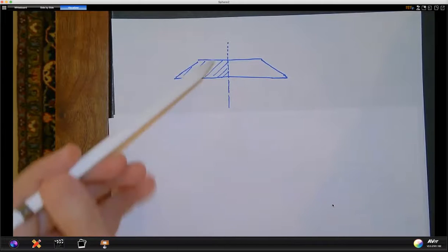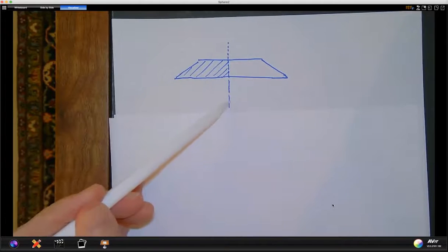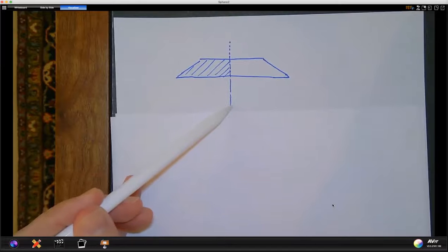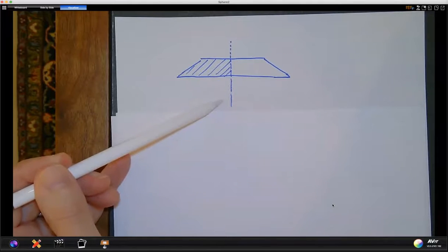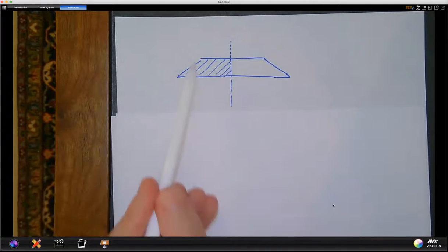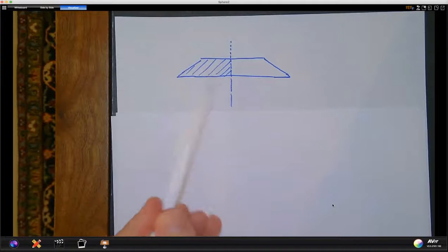And if you happen to be interested in a point down here below the surface at some depth z below the base of the embankment, you can figure out A, B, and Z, and you're off to the races on that family of curves and doing the same interpolation I was speaking of on the other charts.